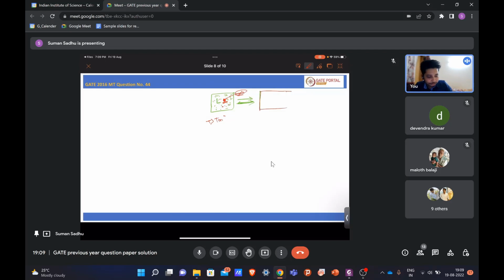Now if you are coming below the melting temperature, that is T less than T_m, let's assume somewhere one small cluster is formed. Now if one more atom joins it, what will happen? If you are above T_m, this cluster will break down. But if you are below T_m, it will further stabilize this cluster. And so this smallest representative is basically called the critical nucleus.